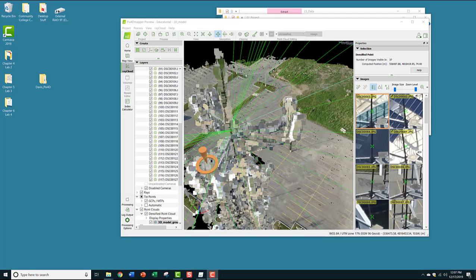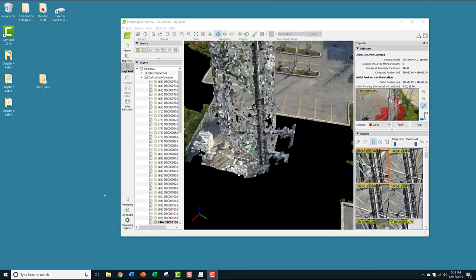The goal of this exercise is to highlight the chunks of pixels that were contributing to the noise, on or near the communication tower. So remain in the carve mode and ensure that your image is in full screen. Now what I want you to do is to zoom into the antenna of the tower and begin to highlight all the features that are not the antenna. For example, I want you to highlight the white building, the parking lot, the vegetation, etc. And remember, the closer you zoom in, the more precise your highlight will be. Try to get near the antenna and highlight all the pixels that surround it.